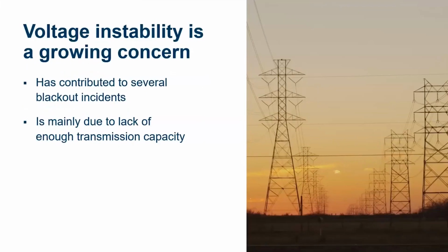Voltage stability is the ability of the power system to maintain steady voltage at all the buses in the system after being subjected to a disturbance from any given initial operating condition. A system may experience voltage instability during a disturbance, such as an increase in load demand or change in system condition, causing a progressive or uncontrollable fall or rise of voltage in some buses. Due to the increased penetration of distributed energy resources, there has been a renewed interest in studying this phenomenon for various system events and responding accordingly.